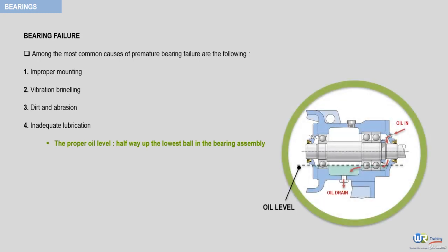Some pumps have a sight-level indicator showing the oil level inside the bearing chamber. It is recommended that you install these indicators if your pump doesn't have them. Teach the operators and mechanics to pay attention to the indicators. As for greases, lithium-based grease is for pumps. Polyurea-based grease is for electric motors. If these two greases are mixed or confused, it will lead to premature pump bearing failure.